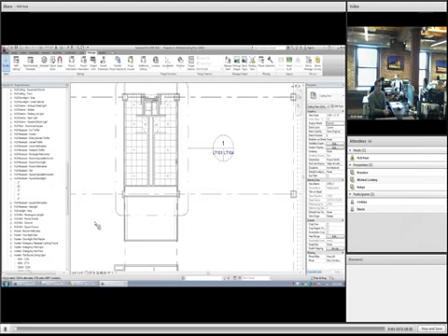And the big distinction is that with the non-hosted fixtures, your HLB fixtures, one issue is that you have to manually set their height. So you have to be very careful about where they are. Unlike the hosted fixture, where you place it on a reference plane or a level, it automatically goes to that point. And we've mentioned before that we can lock it to a ceiling so that it goes up and down if the elevation changes.